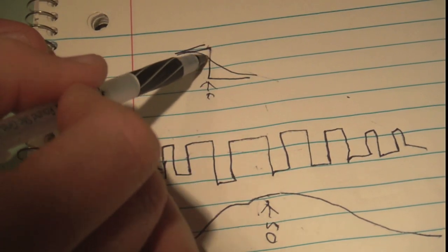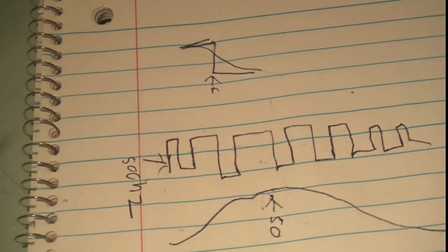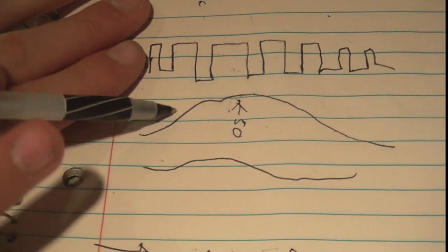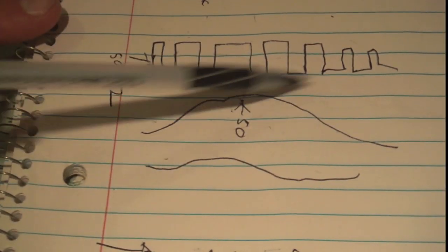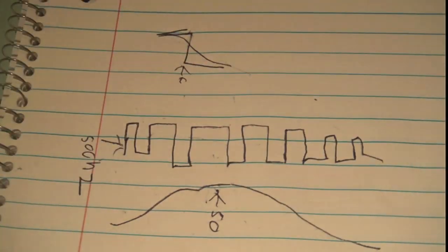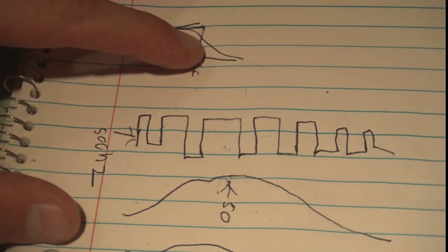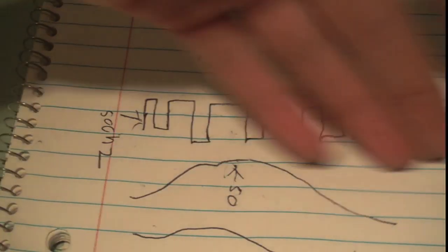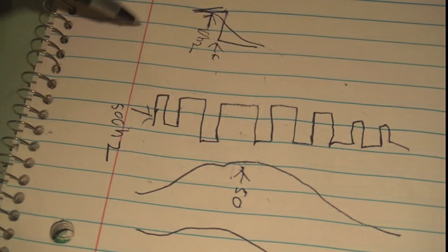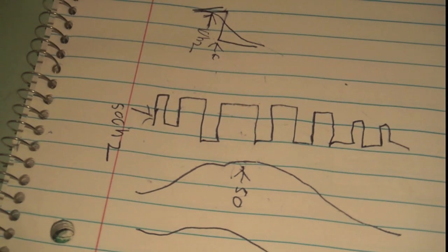And so you notice that, like I said before, the frequencies are going to get attenuated slightly above the cutoff frequency. So if we put 10 hertz as our cutoff frequency, sure, the 10 hertz average will still get through, and the 500 hertz PWM signal will be mostly filtered out. But the 10 hertz signal, all the way through like a 5 hertz signal, will be attenuated some. And that's not good, because we want to make precise analog values here. So we want our 10 hertz to fall more like here. Okay? So we're going to have to set our cutoff frequency higher than 10 hertz to account for this.